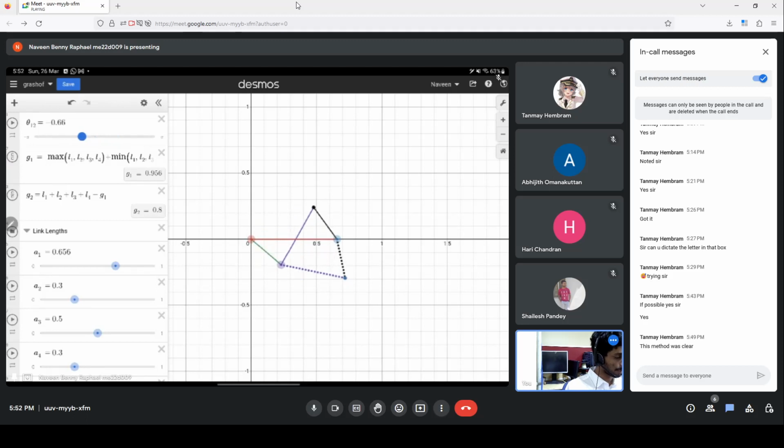So this is a double rocker configuration because you can see that both links are rocking around. If I make this 0.5, G1 is equal to G2, and that gives us the double crank configuration. That is, both the green and the black are doing pure rotations. The green one is going a full 360 degree rotation, and the black one is also going a full 360 degree rotation.